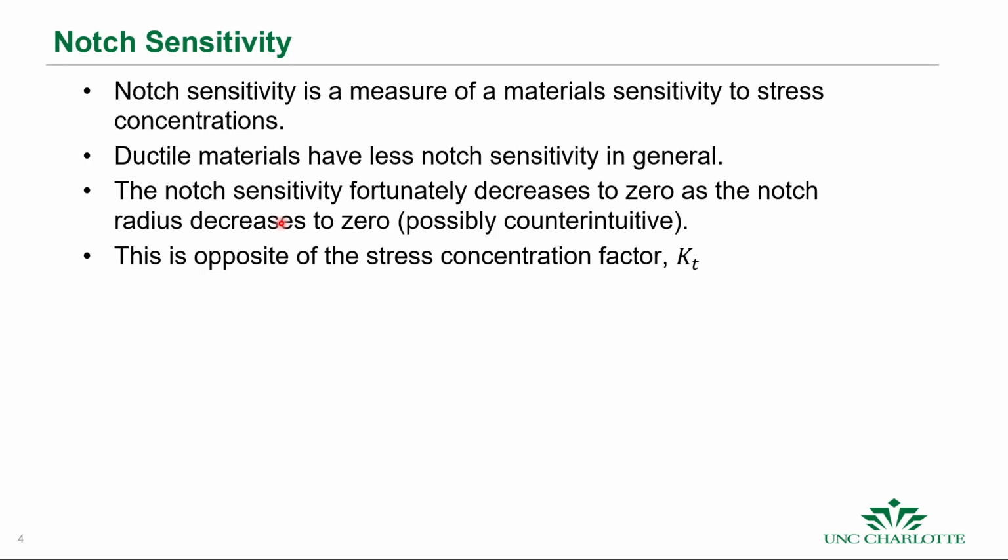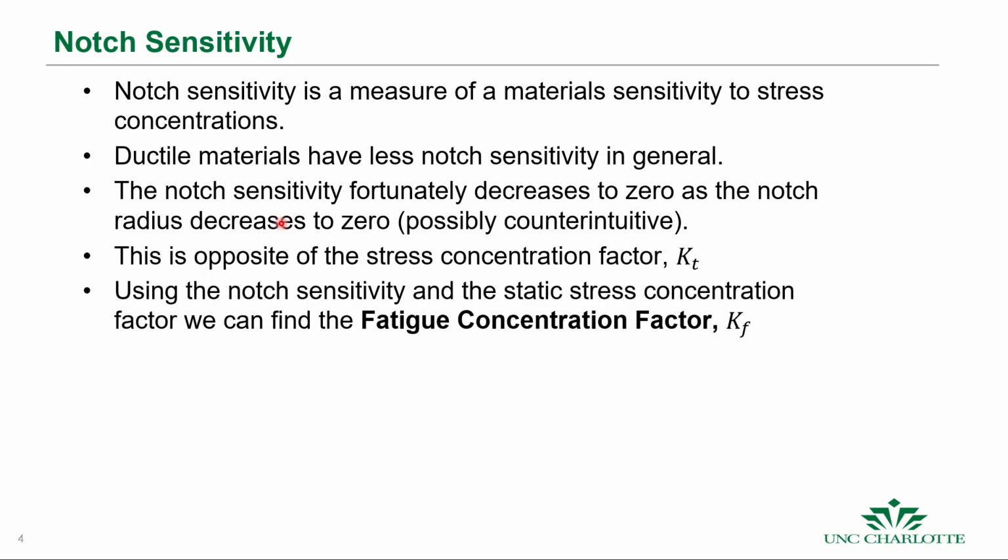That's the opposite of the stress concentration factor. Okay, so it's an important point that when we deal with fatigue, we have this parameter called notch sensitivity, and it has sort of this inverse relationship with the static stress concentration factor. So we'll start with that static stress concentration factor and modify it to get our fatigue concentration factor.